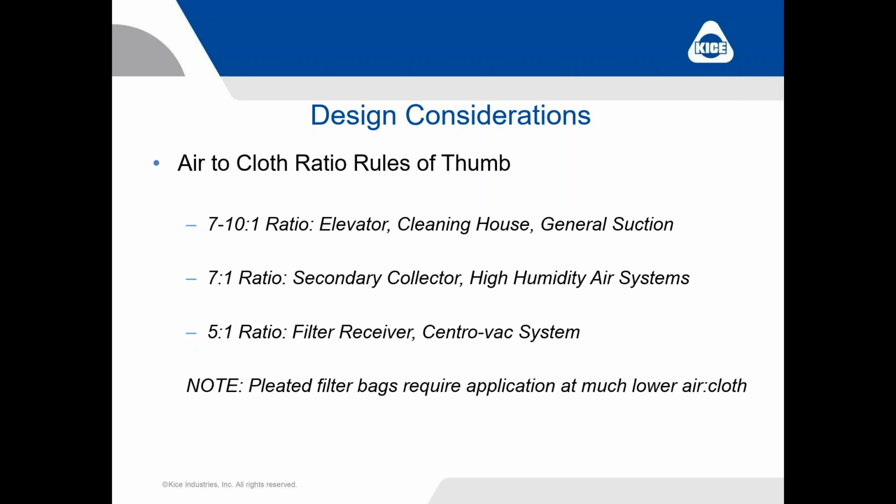And again, your product, your application, your process may dictate that a higher air-to-cloth is okay, or we may need to think about a much lower air-to-cloth ratio. And I will mention, this is the only time I'll mention in this presentation, that pleated filter bags are common for some folks, not standard for us.